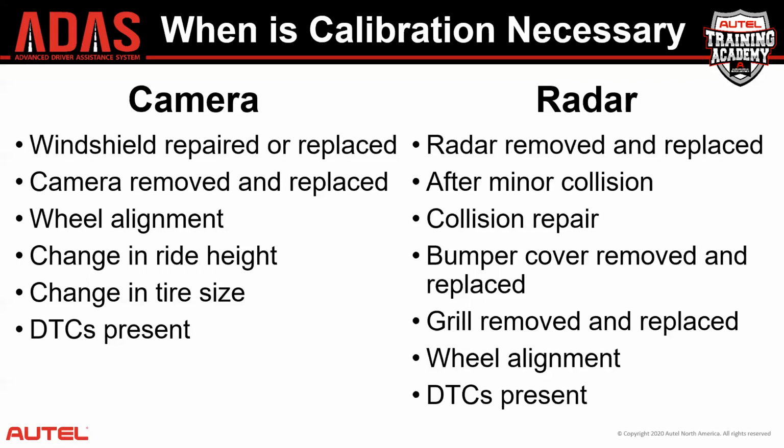You're the professional. You're the one who needs to know what services would be required. This includes changes in tire size or ride height. Anything that changes the ride height of a vehicle from its factory spec may require one or more calibrations.